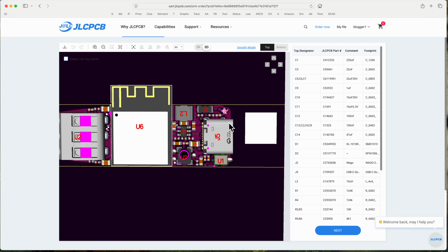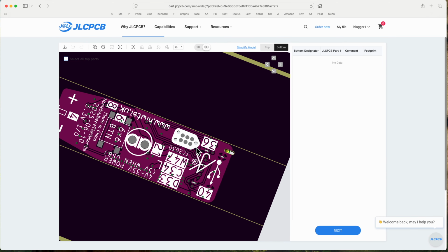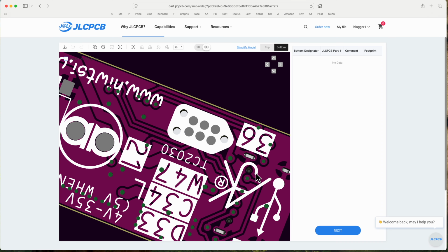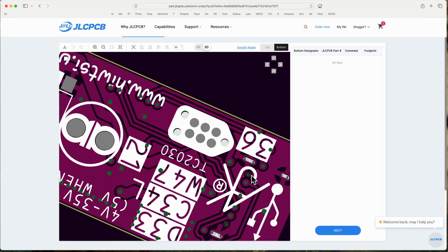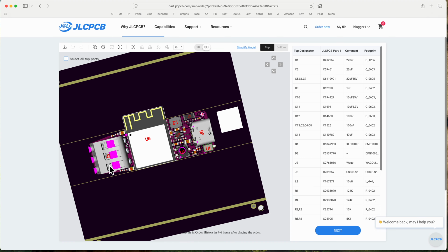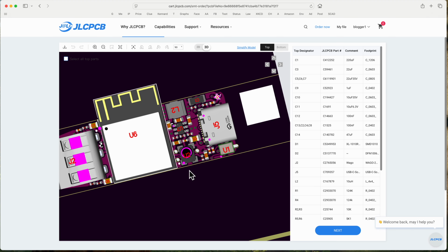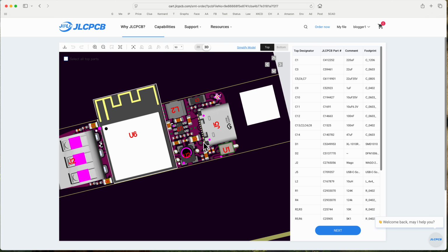But generally, very good. And especially important for some complicated positions, like the position of this USB connector. I can see that it's right. In fact, I can zoom in enough to see that the little plastic nipple in the bottom in those 2 places matches the positioning holes exactly. So I can be sure I've got the position data for that right, and the same for that. So it's really quite important. It also helps you spot that you've accidentally put a large capacitor on small pads by mistake and that sort of thing. You can really see you've got it right.